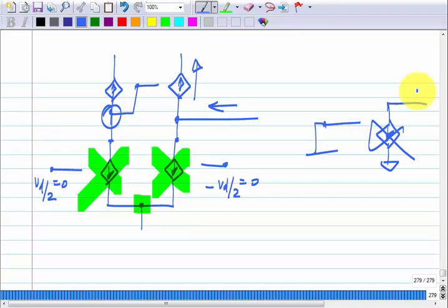So, again exactly the same as the transistor, except that you do not have gate and source which look different from each other. You have two inputs V1 and V2, the gates of M1 and M2. The equivalent will be just a voltage controlled current source of value GM1 times Vd, and the incremental resistance will be infinite, okay. And again, not surprising at all, if none of the transistors has an incremental output resistance, if each of them is a perfect control source, you can expect this type of result, okay.